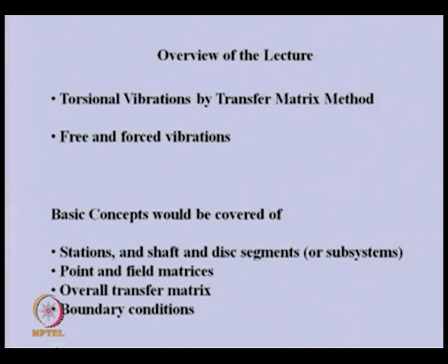Coming to the transfer matrix method or TMM, unlike the previous cases like Newton's method or D'Alembert principle or any other method like Lagrange's equation or Hamilton's principle, in this particular case we try to derive the equations of some segments of the rotor system, like shaft segment, disc segment or coupling segment.